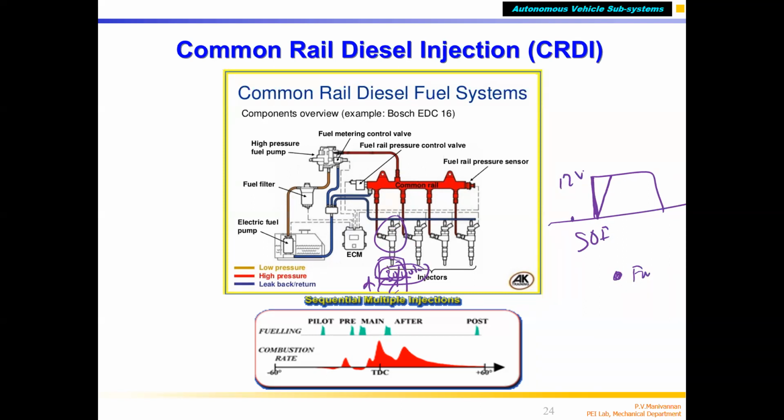So to avoid the pressure drop, I have to open the injector instantaneously, at zero time on this time axis. But the injector is a solenoid, a first order system, so it takes some time for the current to flow and magnetize, just like the petrol injector. So the injector opens slowly, a pressure drop happens, the fuel will not atomize in a better way, bigger fuel drops come, and then you get more particulate matter.